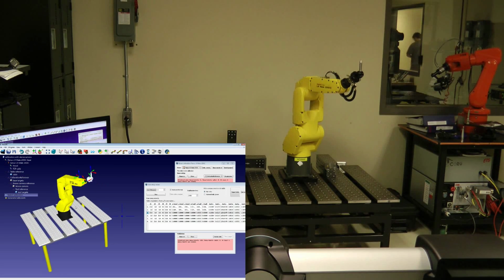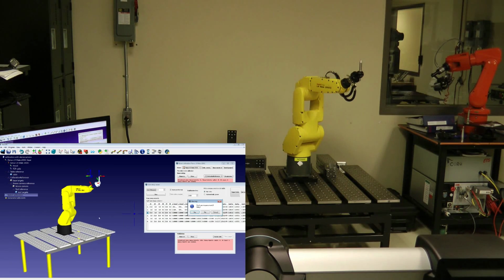If some targets are not visible by the measurement device, we can move the stereo camera to extend the workspace. Moving the measurement device does not have an impact on the measurements because the tool is measured with respect to the base frame.